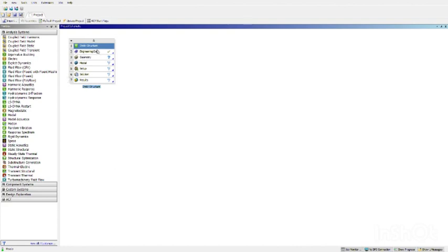So here is engineering data. These are the steps in which we will perform the analysis. The first one is engineering data, then geometry. We will make a geometry in SpaceClaim. Then model, we will import that geometry into our model. Then setup, meaning we will define load, mesh, and all those things. And solution and results, we will see the desired things like stresses and deformations, whichever we want to calculate about our model, our geometry. So first of all, we will start with the engineering data,